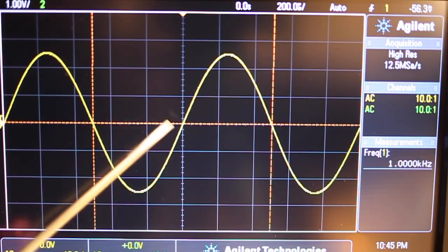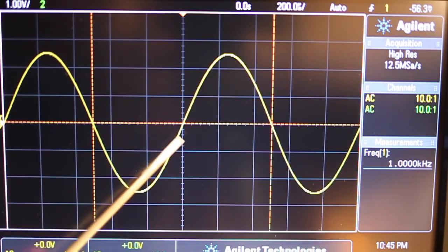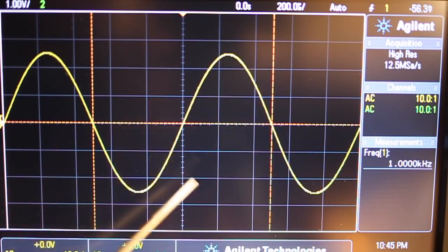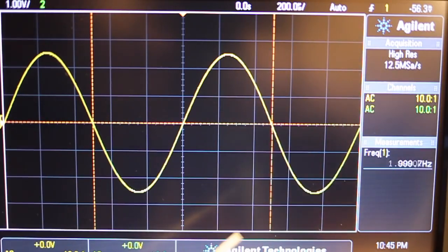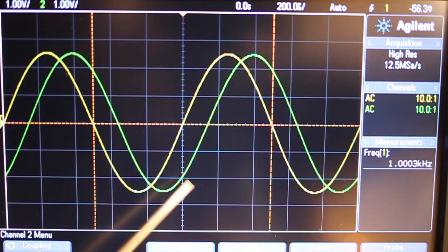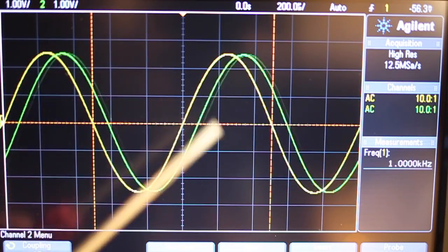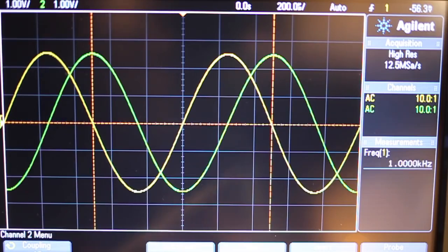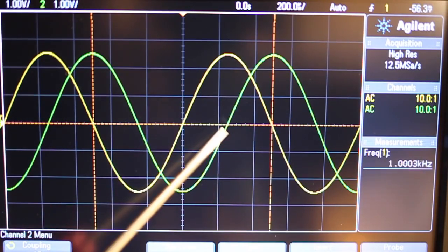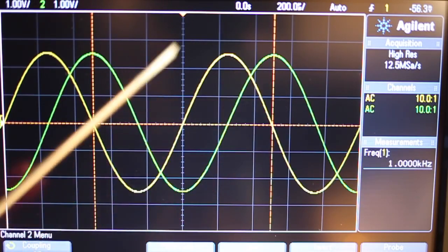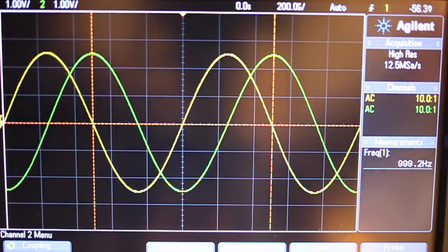Now, maybe if there's a sudden instantaneous change, like a sudden inversion here, you'd see a little blip very briefly. But unless you happen to catch that really brief blip, you're not going to tell if that phase had changed or not. However, if I provide a reference waveform, I can change the phase of that signal, and we can see very clearly that now that we have a reference waveform to compare against, that phase is clearly changing over time here. So what we need is some sort of reference so that we can determine the phase of a signal, because that's the third component of a signal that we're currently missing.